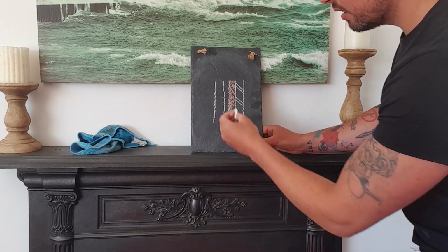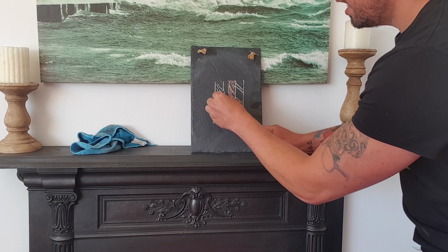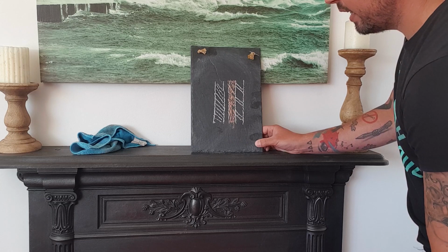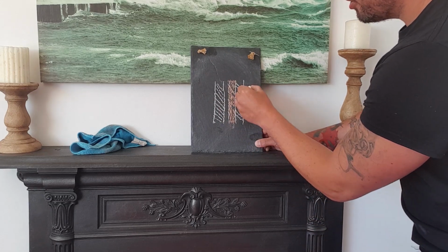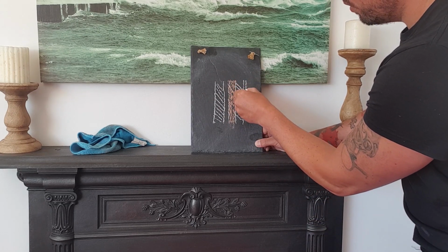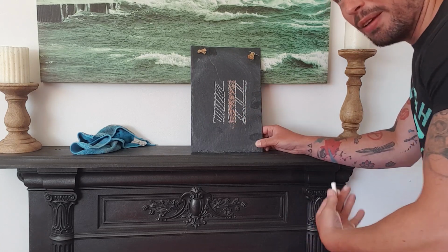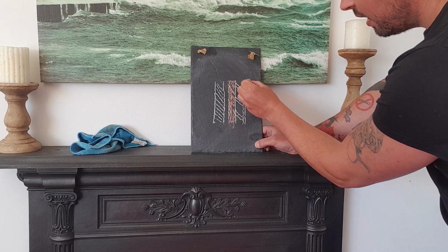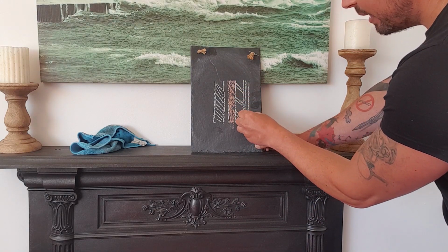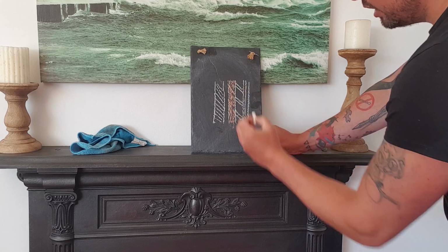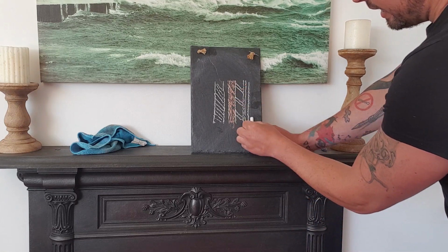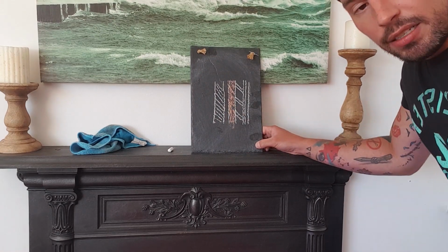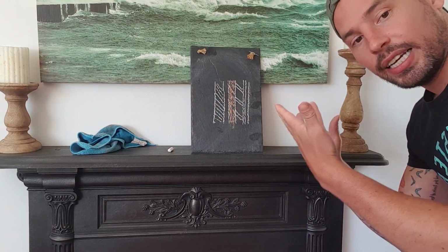Now, in this instance, we've got a brick finish. Okay? And then on the internal side, we'll also have 8mm to 12.5 dab, which is an adhesive for the plasterboard. And then we'll have a 12.5mm standard plasterboard, gypsum based. And then they'll skim 3mm on. And that, my little friends, ladies and gentlemen, is a cavity wall.